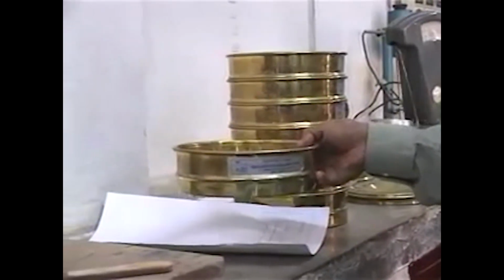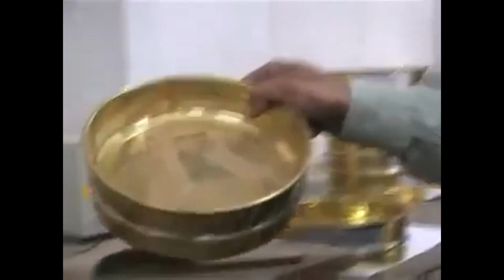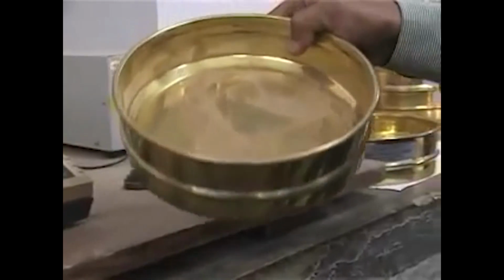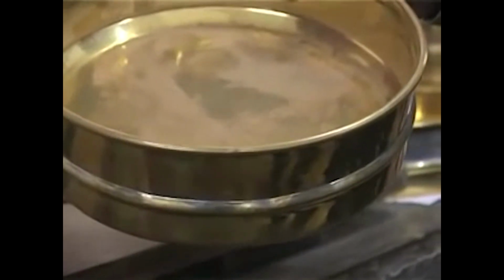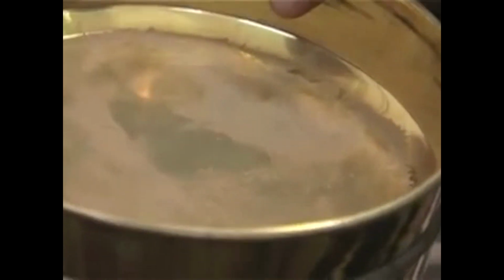Then we are going to proceed to the other sieve sizes similarly, and you can see here that there is a little bit of soil retained past the 75 micron size sieve. The grain size of this particular fraction is typically not determined from sieve analysis. We will need to go on to another laboratory experiment involving a hydrometer for finding the grain size distribution of the fraction of soil which is finer than 75 micron.